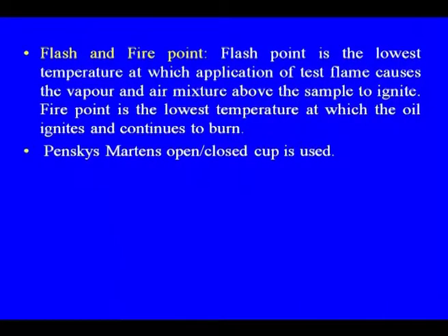Flash and fire point is the lowest temperature. The flash and fire point are very important because we are handling gasoline, diesel or other petroleum products. It is very important from the safety point of view, and at the same time for the quality of the product. Flash point is the lowest temperature at which application of the test flame causes the vapor and air mixture above the sample to ignite. Fire point is the lowest temperature at which the oil ignites and continues to burn.